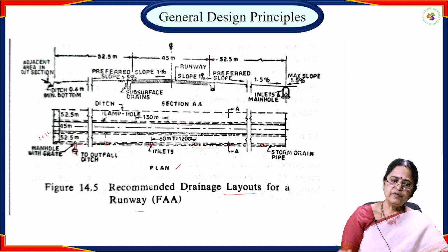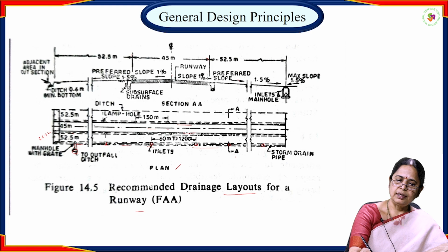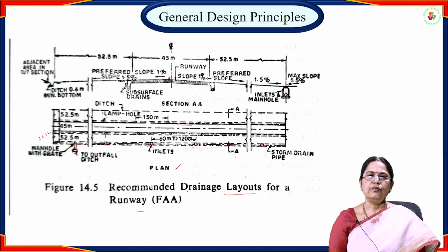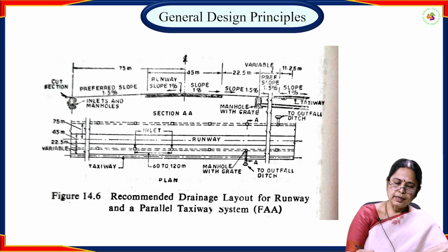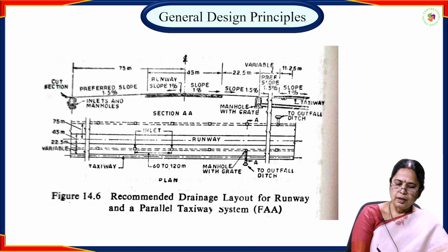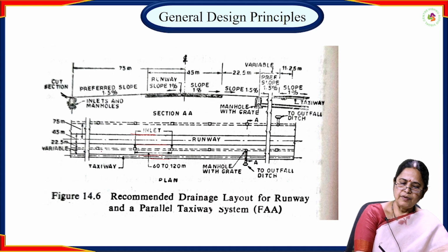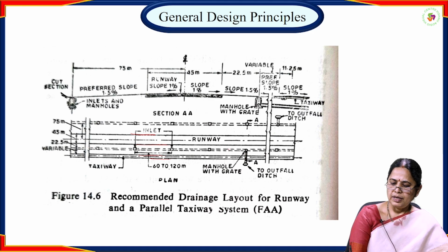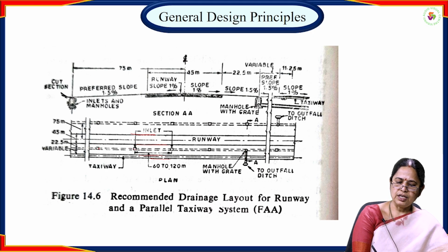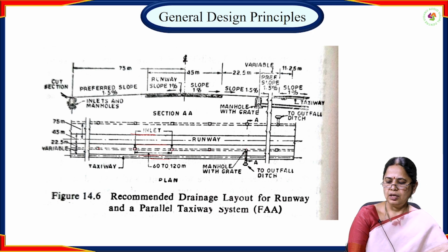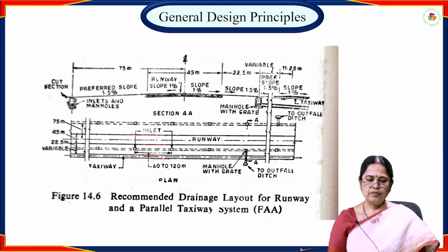So the time of inlet is nothing but the time taken by the storm water from the most remote point to the inlet of the manhole. And in case of a taxiway running parallel to the runway, a valley is going to be constructed here, and also these drainage inlets are going to be placed in the valley in between the runway and taxiway.